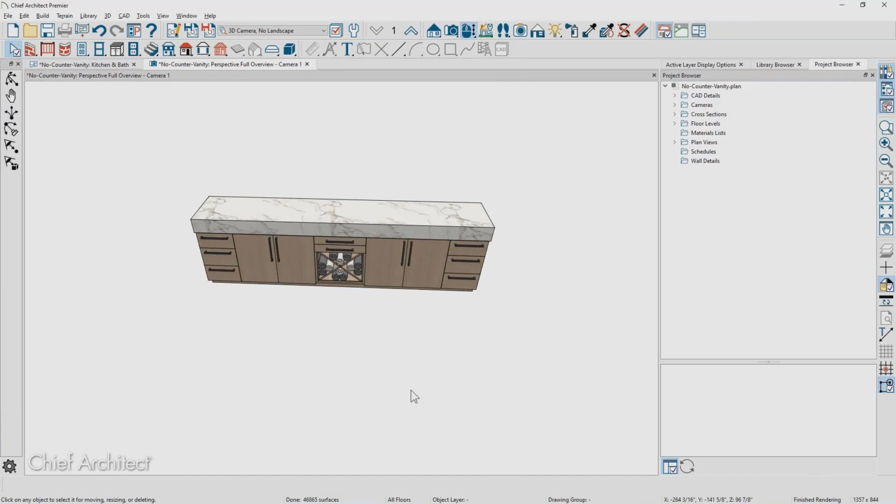As I mentioned, when you do your subtraction of the 3D solid, you need a custom countertop. And in my challenge, since my cabinets already had the automatic countertop, and when I did that subtraction, it converted the countertop to a solid, and then the automatic countertop returned because the cabinet saw it didn't have a countertop. So a couple ways you can do that with the countertop.